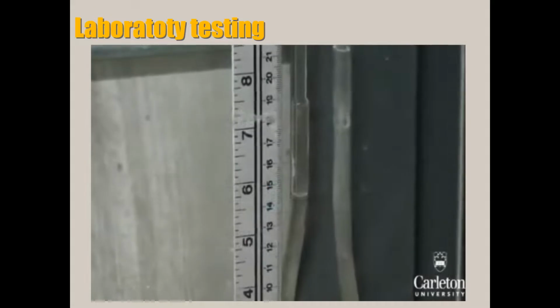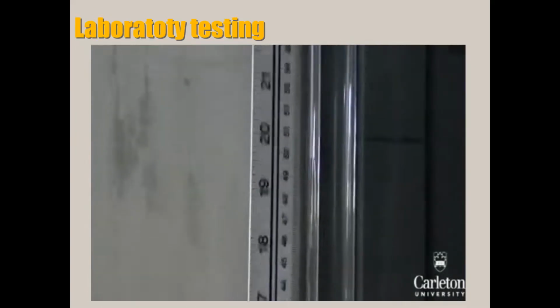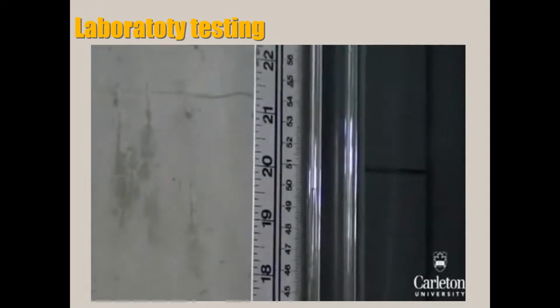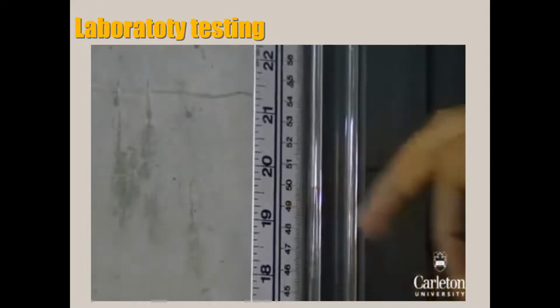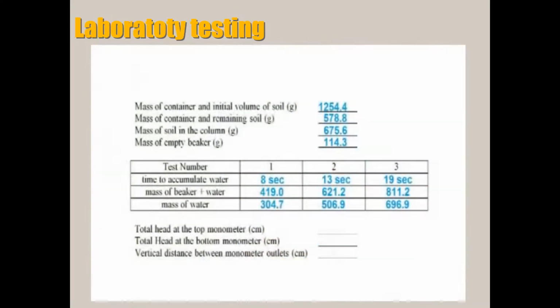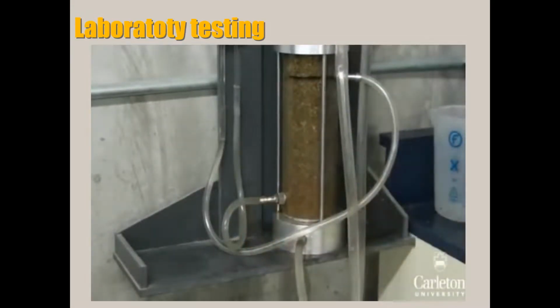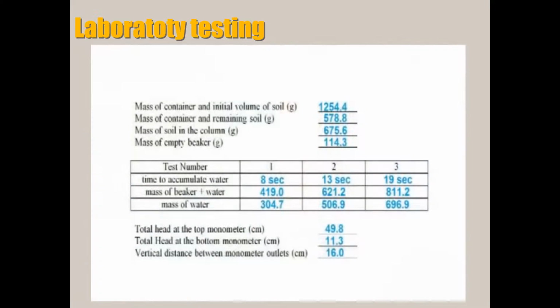Before we finish, we need to calculate the head applied to the sample. To do this, measure the total head at each manometer from the base of the cylinder. Here the head height of the top manometer is 49.8 centimeters, and 11.3 centimeters for the bottom manometer. Finally, record the difference in height between the outlets to the 2 manometers. You can draw a line around the outside to help you do this. In our case, this was 16 centimeters.